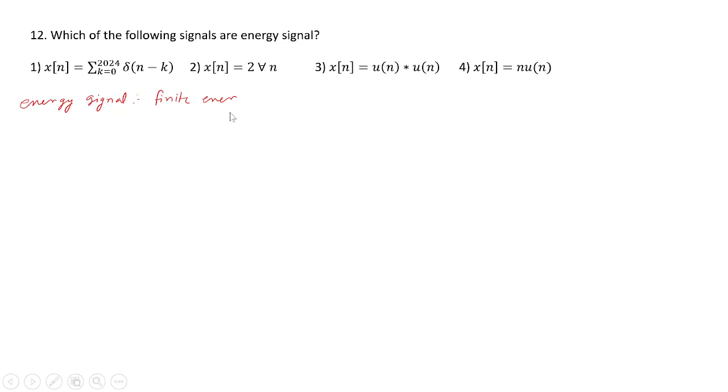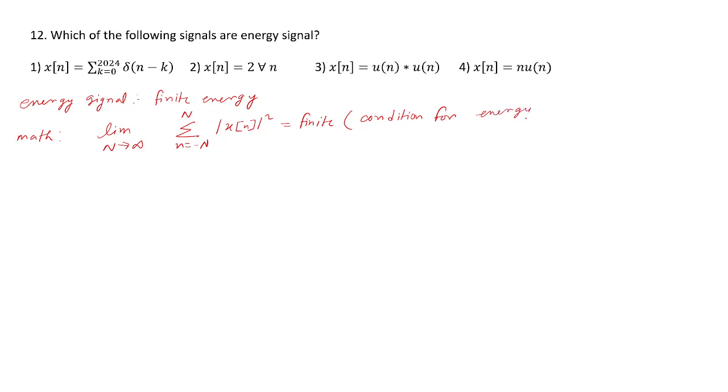Mathematically, the limit as N tends to infinity of the summation over small n from minus N to N of the squared magnitude needs to be finite. Condition for energy signal: